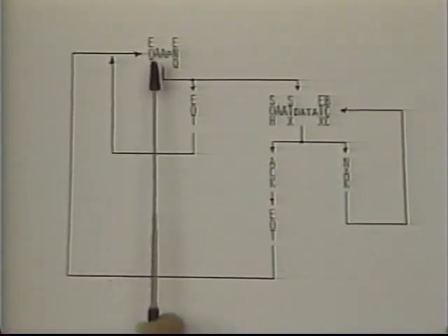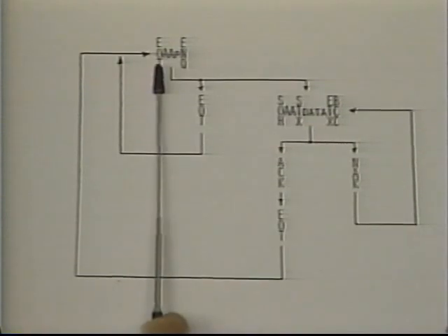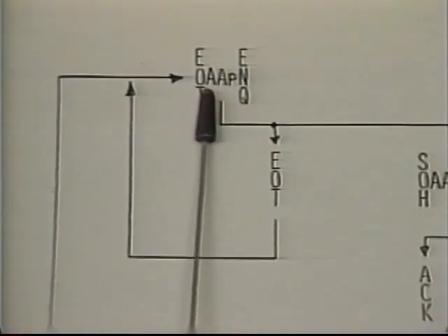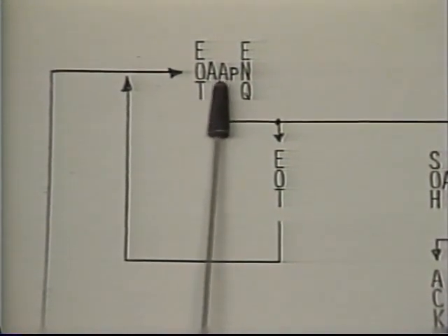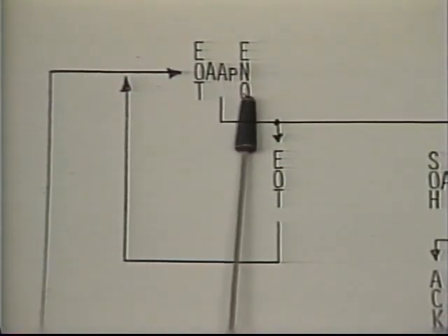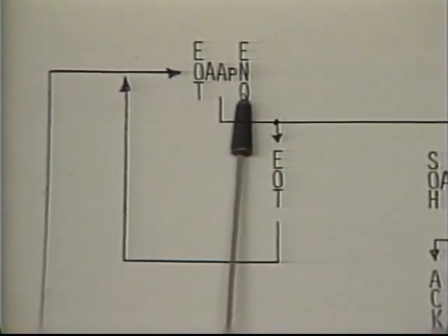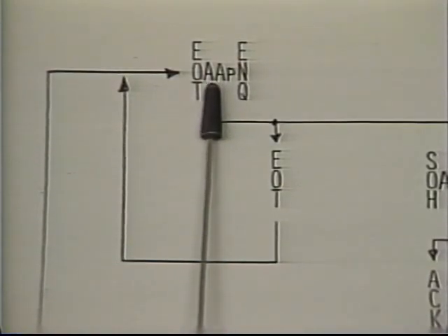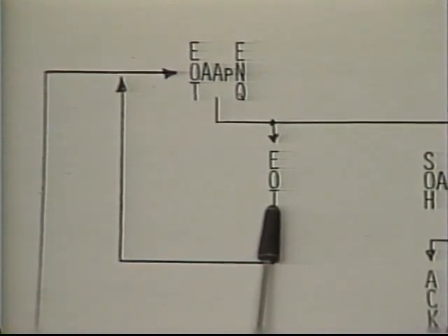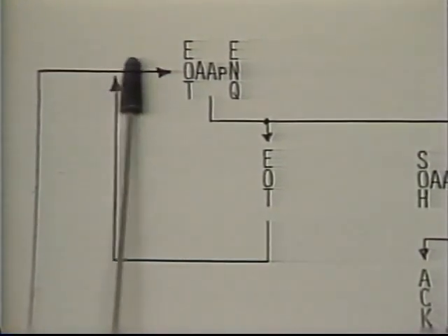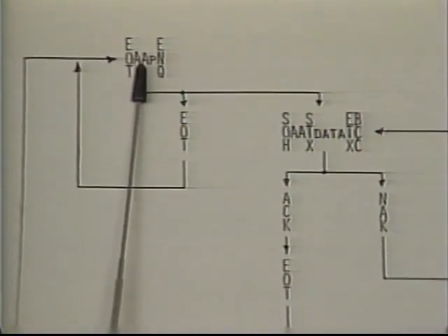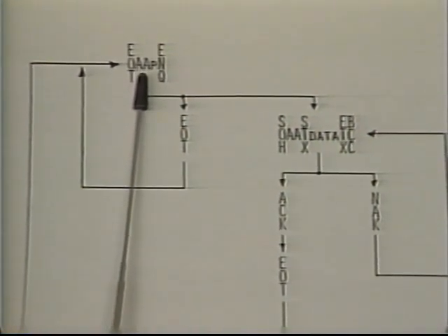This is a copy of the chart for the ANSI protocol for polling. In this particular case, we have a 5-character message which goes out from the computer polling the remote station. The message begins with an EOT and has a 2-character station address, a lowercase p to indicate it's polling, followed by an ENQ. When this message goes out, if the station AA did not have anything to send back, it would send an EOT saying, I have no traffic. When the EOT comes back, the computer would now change the address and poll the next station in sequence.